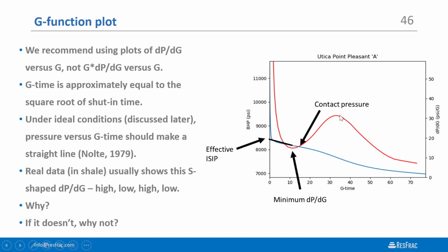So as we get deviation from Carter, leakoff is happening more slowly than you might have expected because pressure has been falling off, so you have less driving delta P. That causes the leakoff rate to drop off, and so late time dPdG goes to 0. So that's why you get an S. Near wellbore tortuosity, ideal behavior preclosure, contacting a fracture wall stiffens the system, and then deviation from Carter leakoff slows down leakoff. That's every bend in this curve.